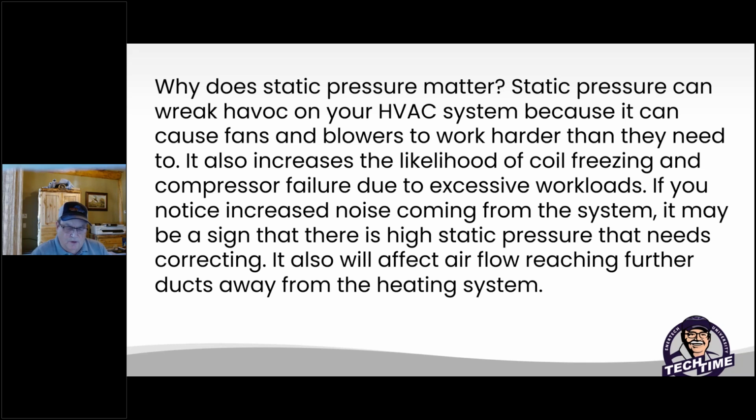Also, when you have a zoning system, there could be a malfunction in here as well. Let's say we've got a damper closed or something that's not opening, that can create this. One important thing when you're designing some of your dampering systems or zoning is bypass dampers. Take a look at all your airflow going into each branch and make sure that your blower can handle it and is not under excessive loads.